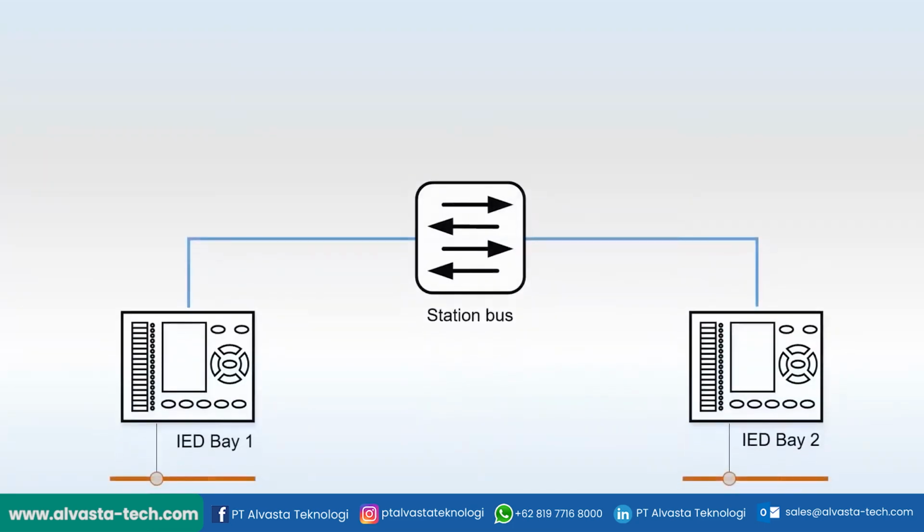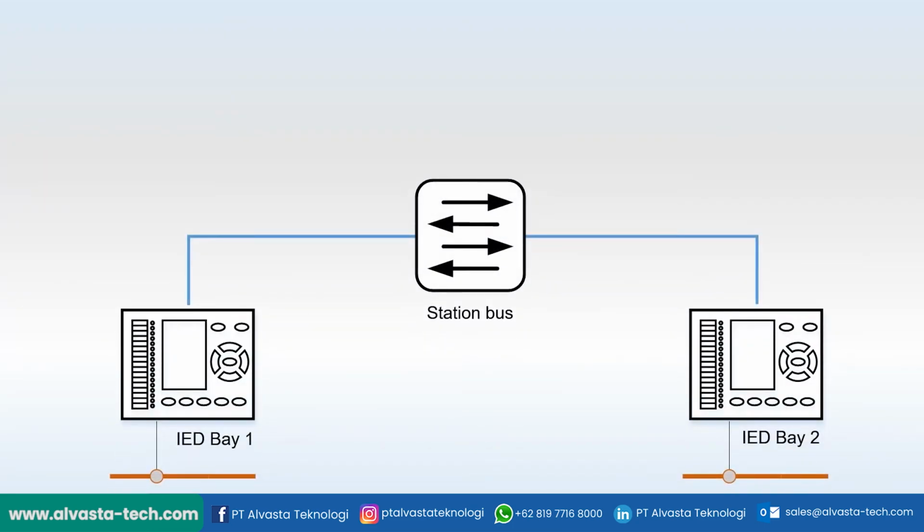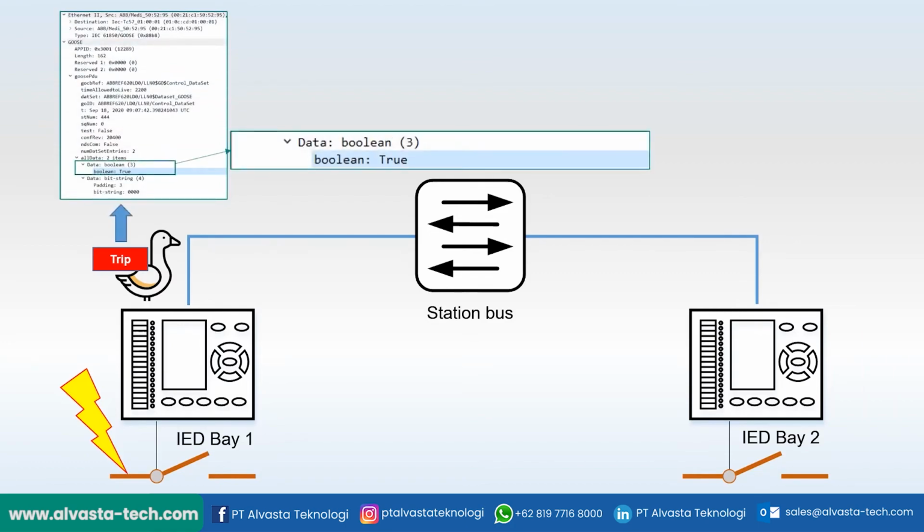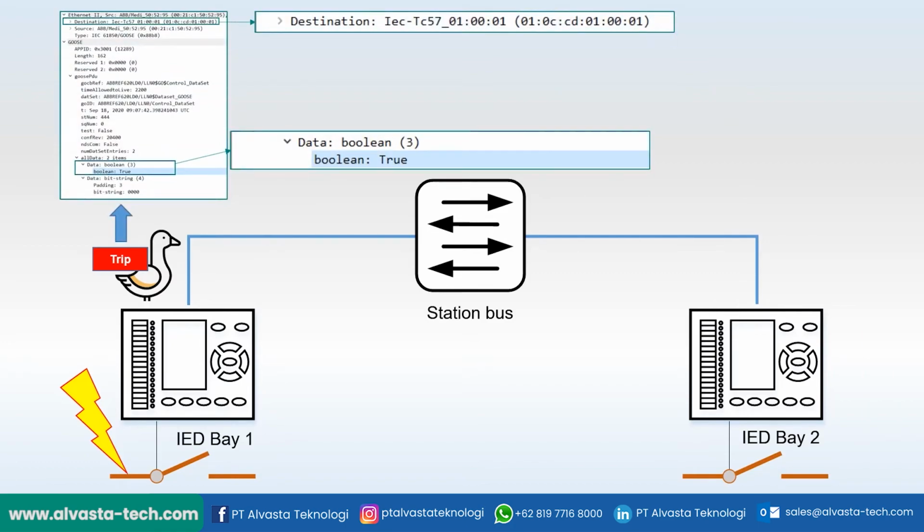In the first scenario, I exploited the IED-to-IED communication protocol, which is called GOOSE. It is used for one IED to report its status to another IED, so protection functionality can span different areas of the substation. If there's a failure in one bay, the other bay's protection should react accordingly. GOOSE was originally designed unencrypted because of its time-critical nature. There is an additional standard which implies digital signing of GOOSE messages. However, it's not widely adopted yet.